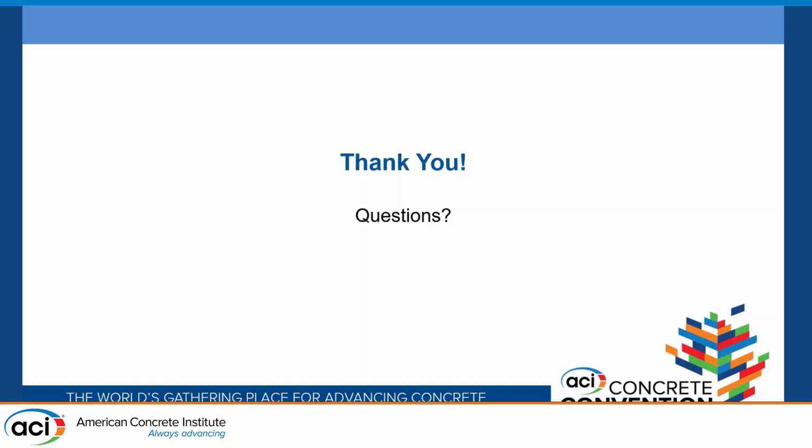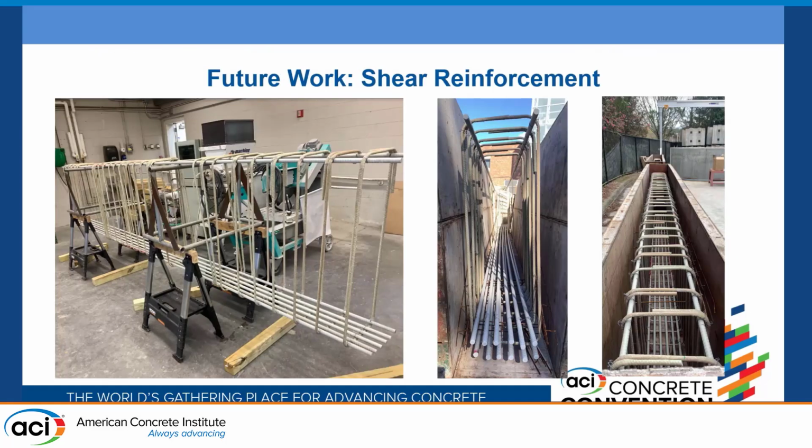Okay, let's start here. Thank you for a nice presentation. I have a couple of questions. The first one is, when you showed the reinforcement of the beams, ACI 440.11-22 says that if the depth of a beam is more than a certain amount, you have to have skin reinforcement. And you don't have skin reinforcement here. Just because you're doing research, you want to see what happens without skin reinforcement, probably.